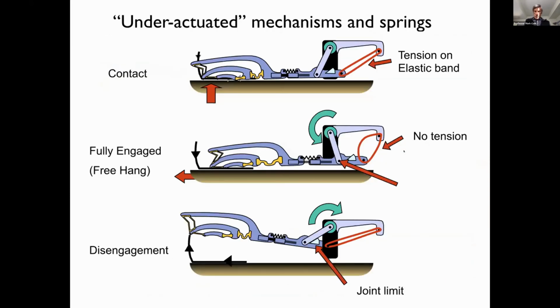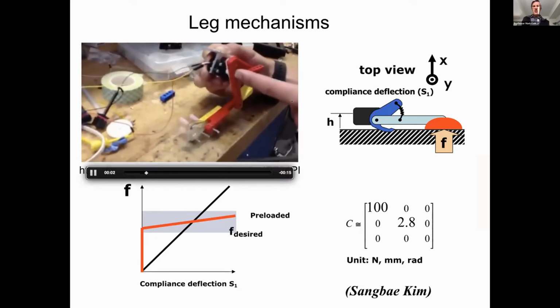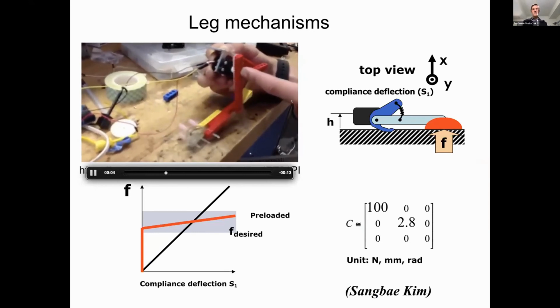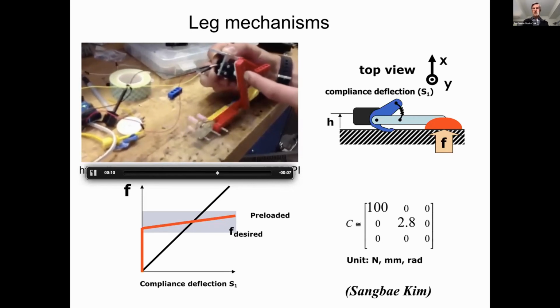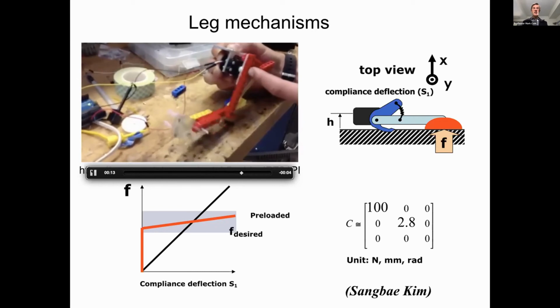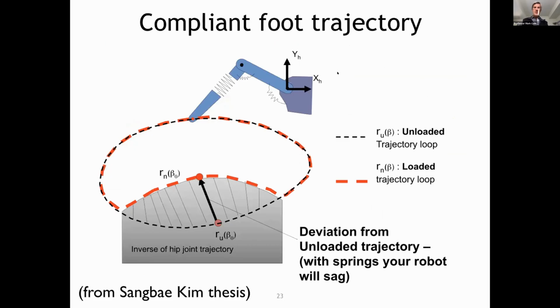Okay, well, one of the things we needed was to minimize the number of actuators, so a lot of interesting work on under-actuated mechanisms so that we got a desired stroke with just one actuator. Again, this stuff with the equations is in a paper, but what many fewer people have seen is the very early prototyping using Legos. Now you see we're back to that critical function prototype idea. And by the way, that's one of the things that we tell students: the critical function prototype stage does not end. You just wind up using it on different things as you go. And this gets refined. This is a slide from Song-Bei's thesis, building some theory around what we started to observe.